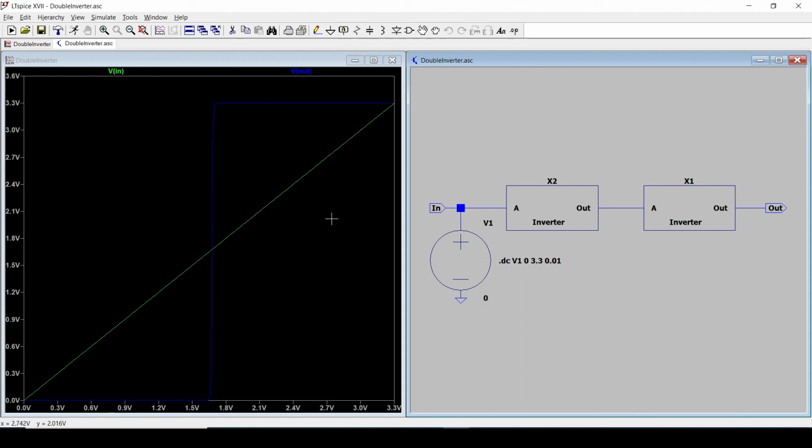Now in terms of analyzing the RS latch, the key point to look at is if we connect the output all the way to the input, when do we have consistency? When can I join the output to the input and stay in steady state? Well, that means we're looking at points in this diagram here where the output voltage exactly equals the input voltage.